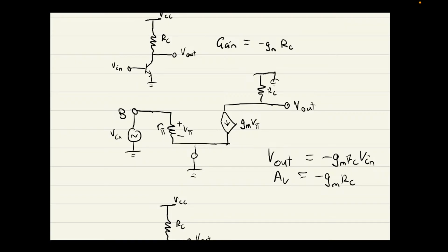Okay, I want high input impedance, low output impedance. I can use an emitter follower for that, and it has unity gain as well. But yeah, hope you found that useful. We'll move on to Leif now.